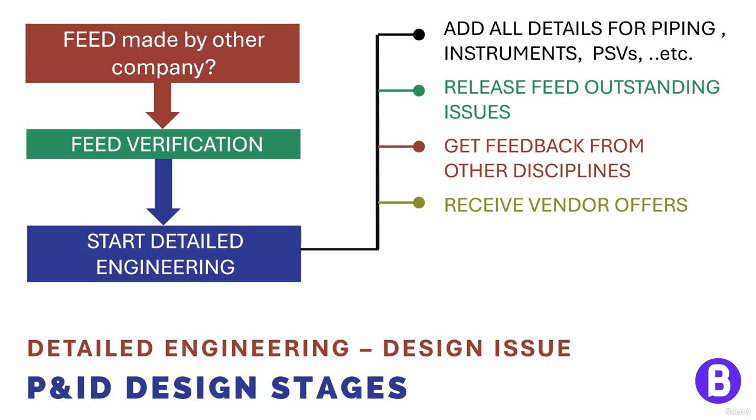For example, the pump vendor may supply curves that require a shut-off pressure, which is higher than that of the equipment or piping on the pump discharge. This shall mean that we should either increase the design pressure of the discharge system or add protection to avoid overpressure, such as a pressure safety valve or a shutdown protection at high pressure.